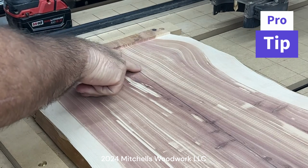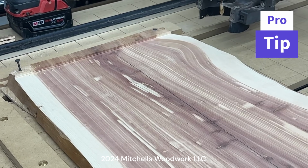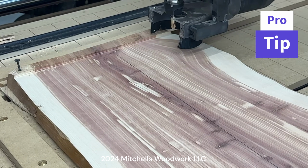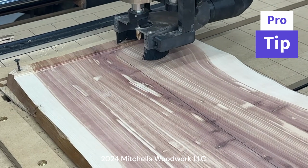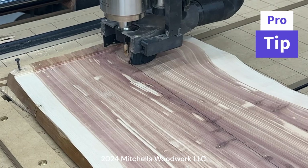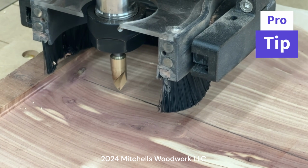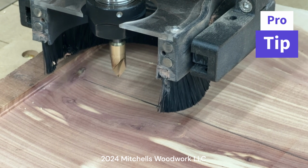All right, see the pencil mark through here. I'm going to move the spindle up here. That out of the way. And I just got to put that V-bit down on that line. All right, I'm on that line. So now, I'm going to raise it up just a hair. Now I'm going to run it all the way to the other end of the slab.